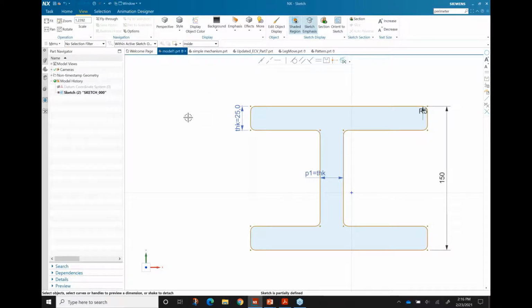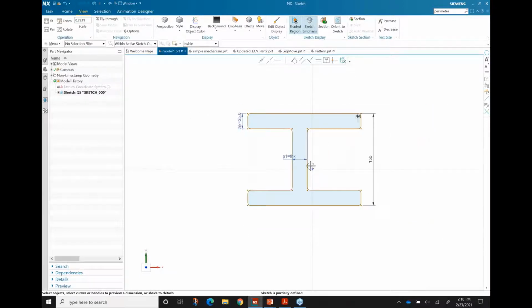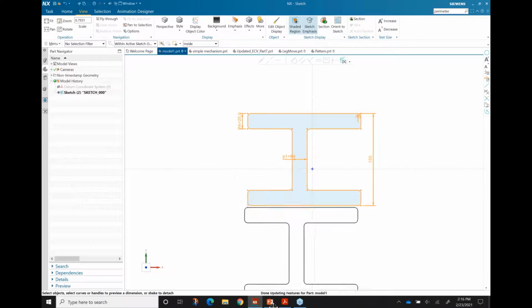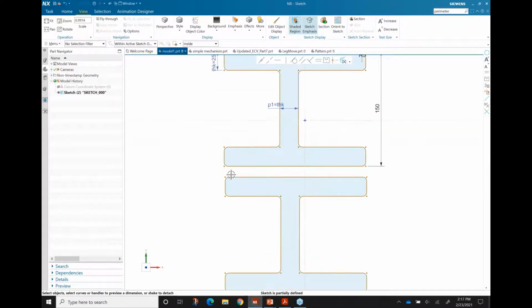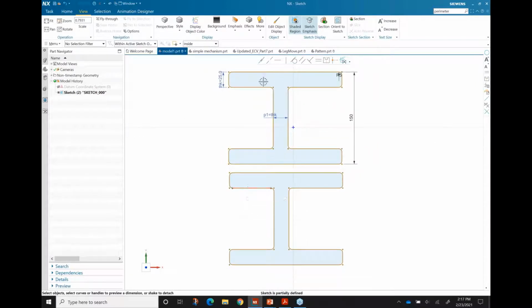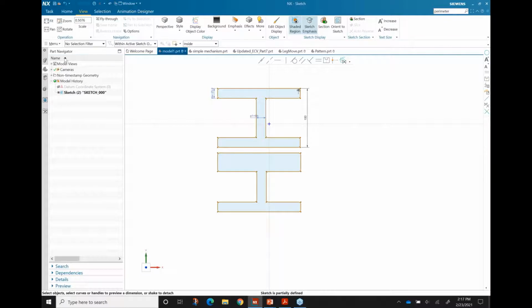Let's look at a couple of other things that we can do with our sketching. So one thing I'd like to show is if we were to highlight, put a box around our entire sketch, and then hold down the Control key, it actually gives us the option to copy an entirely new version of that sketch. So if you have some feature and you want to just have another version of it, very easy to do. And then we have this part. But what's nice is I can even take and line it back up, and now everything's aligned. Once I aligned it once, the solver says, well, everything else is in line too. Surely that's what you want. And it's right, that is what I wanted. Hopefully you're getting to see that this version of NX, it's just really powerful.